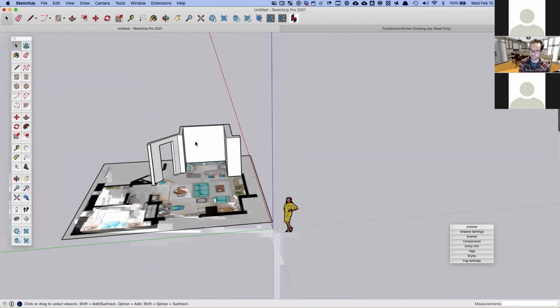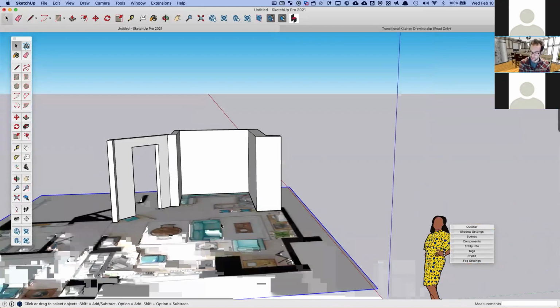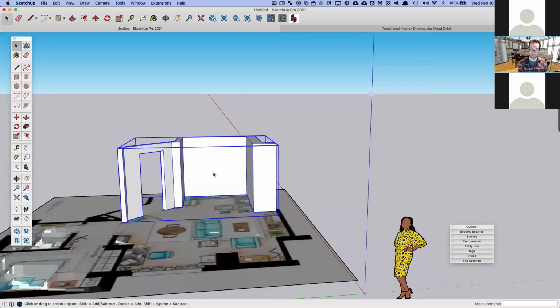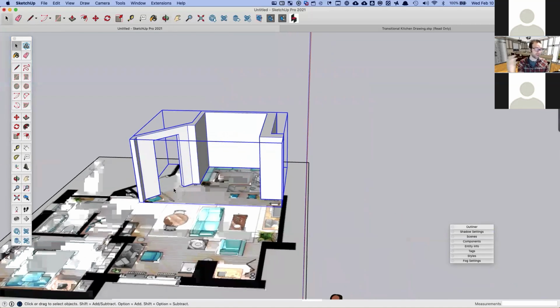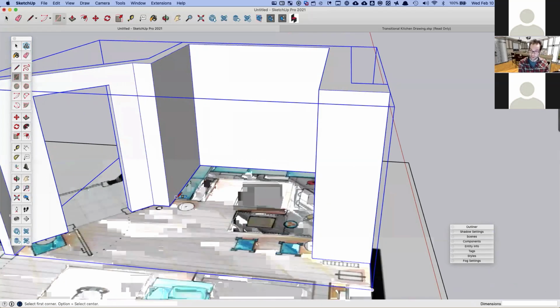So we'll go over here. This floor, which I kind of glossed over in the beginning, is already in a group. This floor is protected. It's got a little force field around it. So if I click and drag and select this section of wall, I can right click it and make it a group. And now you can see it's in its little bounding box and it's safe and protected from everything else. So now I can go back and make that refrigerator that we just made.